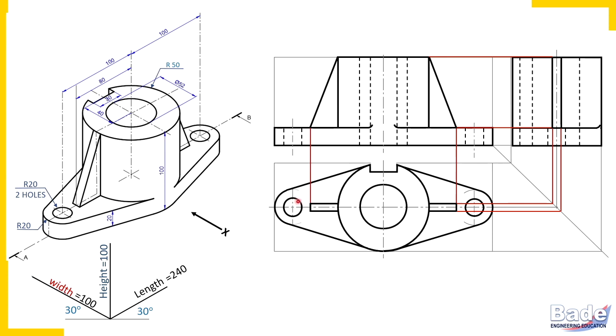We have completed this drawing, but actually in this topic we are going to study sectional view. We are asked to draw sectional front view. Also these two arrows suggest to you that the section is visible from front, and the portion nearer to the observer, that is of course the front portion, is to be removed.